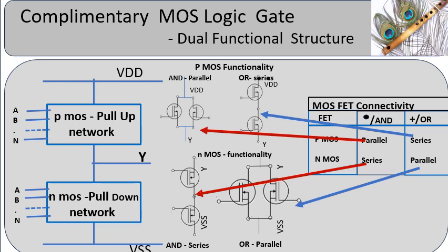CMOS logic gate circuits are built using a combination of P and NMOS transistors that operate in complementary configuration. CMOS transistors operate in common source mode and provide phase inversion, which is an integral part of a CMOS structure. The desired logic function is implemented using pull-down NMOS switches. Its complementary function is created with pull-up PMOS switches, and the CMOS logic gate produces the inverted desired logic function.